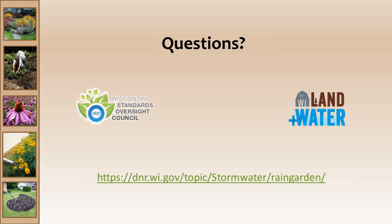Perry's already mentioned it. In the business of working with nature and trying to put a lot of water in a place and have it infiltrate and do some work for us, we've always found a need to be conservative. So 2 inches an hour was selected as a conservative number.